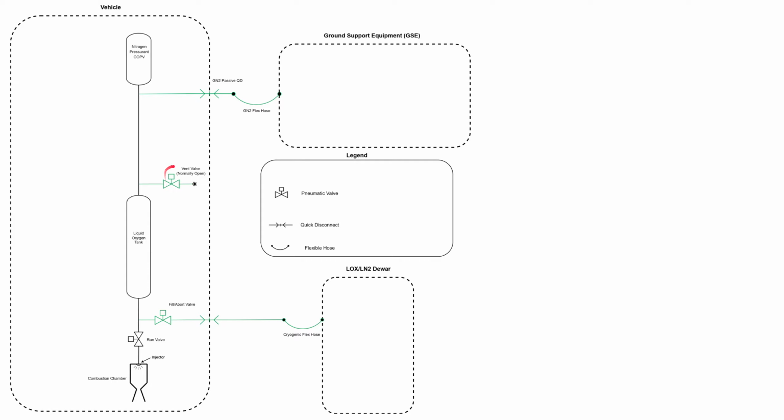Both of these valves are the second and third valves that we designed and machined, and they are both normally open, which is different than the run valve, which was normally closed. Normally open just means that under regular conditions, the spring is pushing it open.